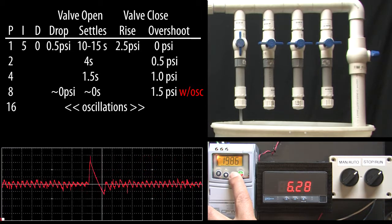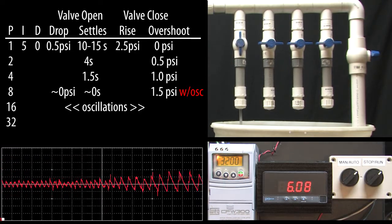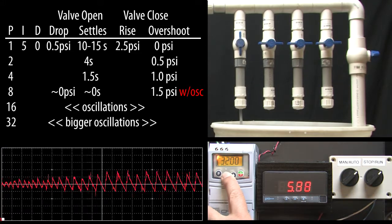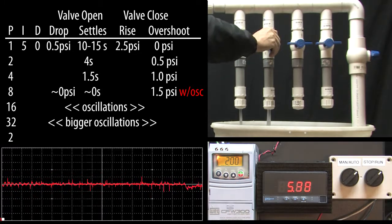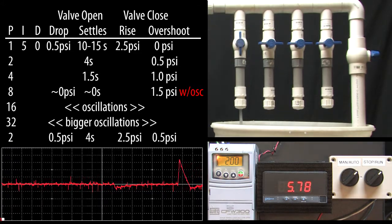So just for fun, let's push it even harder and double the gain again. If I turn up the sound, you can even hear the water pulsating. Okay, enough of that. I'm going to turn the gain back down to something stable like a 2 before something breaks. I'll open and close the valve, and sure enough, we're back to our super stable, reasonable response. Now I kind of like this because it's faster than the 10 to 15 seconds we were seeing with the default PID values, and the overshoot here isn't any worse than the pressure drop here. That's a pretty good compromise.